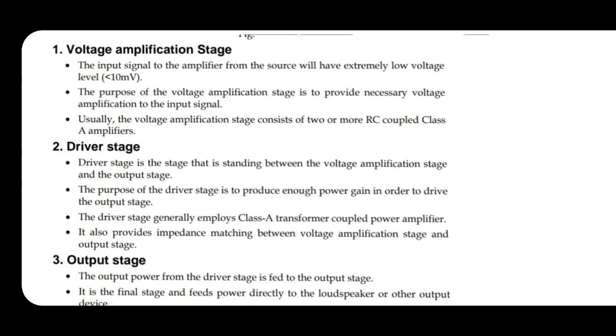Now the voltage amplifier stage. The input signal to the amplifier from the source is extremely low. The purpose of the voltage amplification stage is to provide the necessary voltage amplification to the input signal. Usually the voltage amplification stage consists of two or more RC coupled amplifiers.